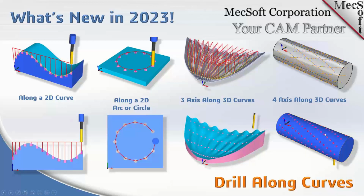And then I really like this, the ability to do it in 4-axis. If you have 4-axis geometry and you need to put a pattern of holes, you can do that with curves that lie on your part and along the radial axis, as you see here in the top left corner. But also in the demo, when we do it, you can do that along a curve going across the 4-axis part as well. So that's pretty cool. No need to do the index machining.